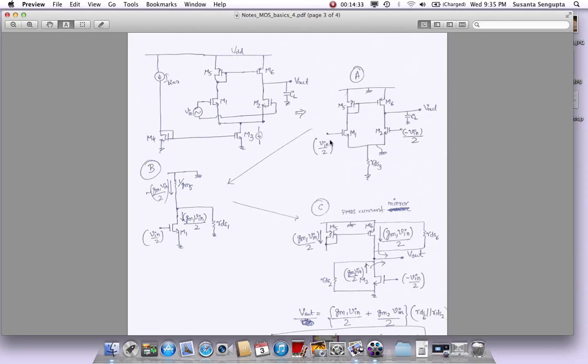So differential, if you put them together, it becomes Vin, and since this is acting as a current source, there is no change in VGS, it's constant because this is a constant DC bias, so this becomes an RDS3, but we can also neglect this RDS3 because this is AC ground. We have two equal magnitude but opposite polarity signals, so the middle point automatically becomes a ground to a differential signal. So this can be further simplified here, and what I'm trying to show is I'm going to take a part of this circuitry and try to show how the current is generated in one part of the circuitry and how the small signal current is flowing.